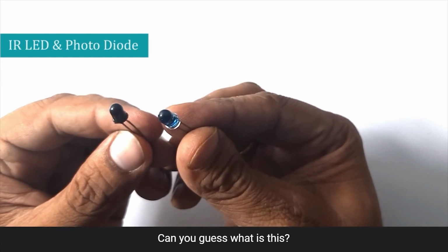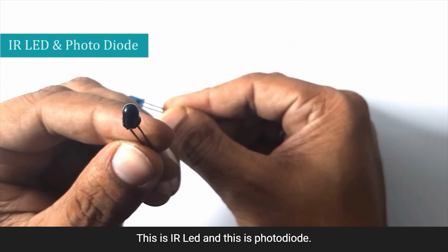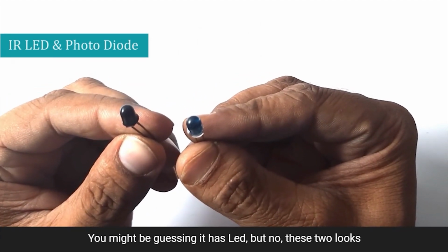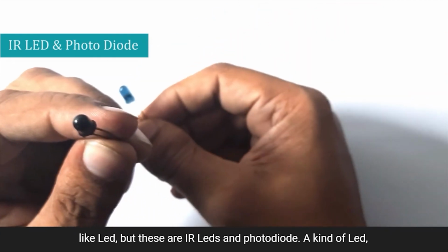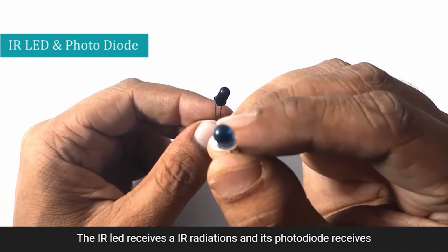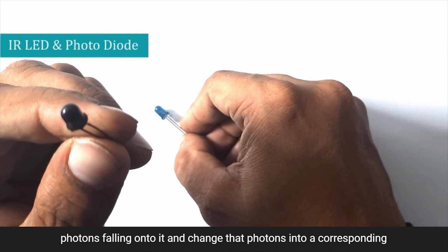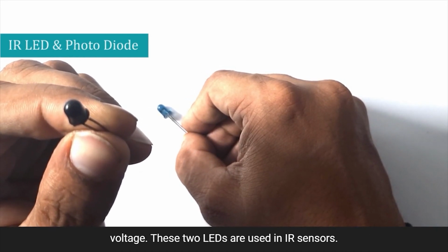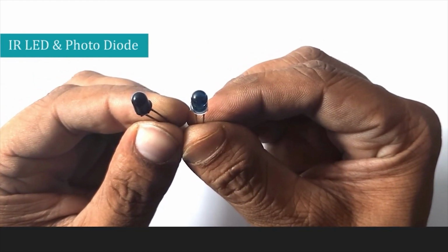Can you guess what this is? This is an IR LED and this is a photodiode. You might be guessing them as LEDs, but no. These two look like LEDs, but these are IR LEDs and photodiodes, a kind of LED but with different properties. The IR LED emits IR radiation and this photodiode receives photons falling onto it and changes those photons into a corresponding voltage. These two LEDs are used in IR sensors.